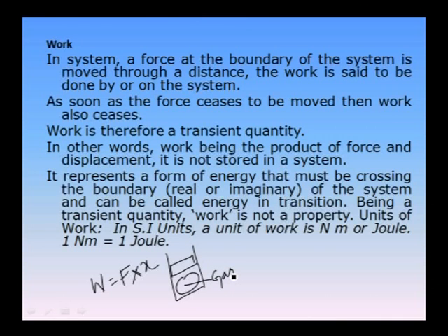Because of expansion, force is produced here, causing the piston to move a certain distance x. So, this is the boundary, right. When the force at the boundary of the system is moved through a distance, the work is said to be done by or on the system.